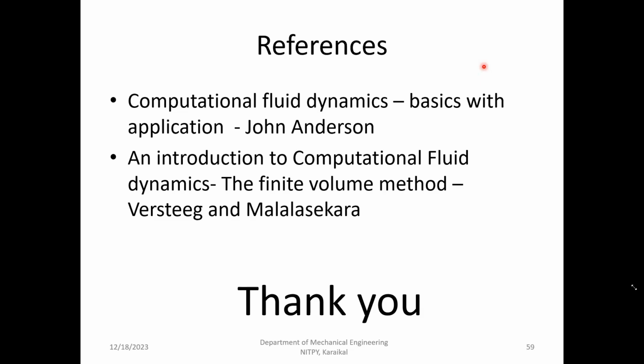Okay, drilling characteristics. If you're going to look at tool removal and heat transfer in the tool, it's going to become much more complex. With Fluent, it's going to be very difficult. We have separate tools for it because in Fluent, we have a mesh which is stationary. Now in drilling, the drill bit moves and also the material is going to be removed. So that's going to be a chipping of material. To include all those things in Fluent is very difficult. So you have other additional software to do that. You can use that one.